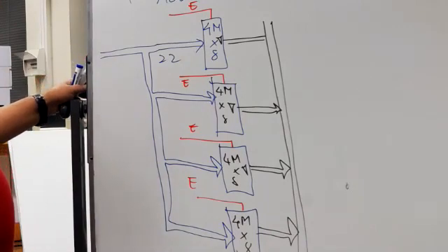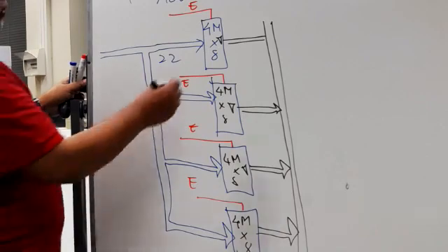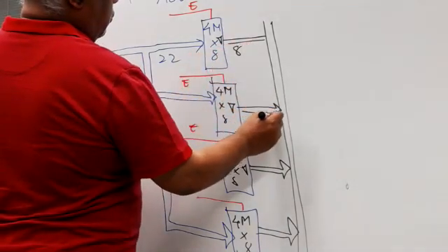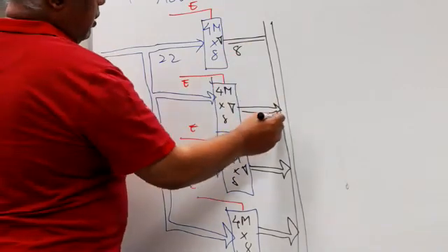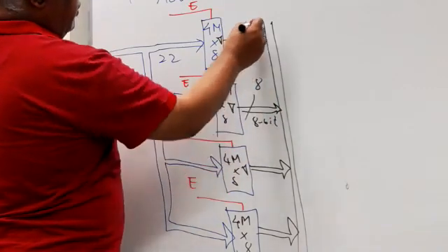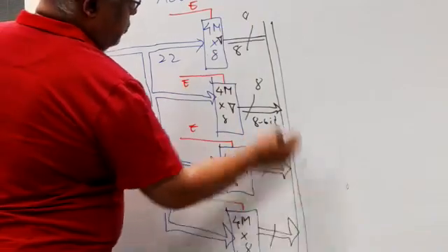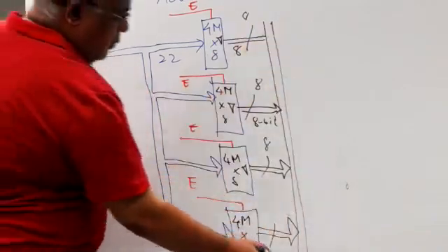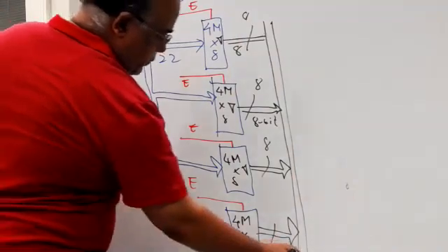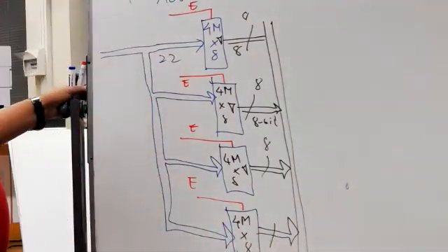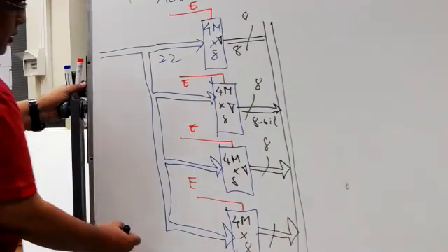Since all of them are 8-bit data buses, that's why you are using this tri-state very nicely. This tri-state property of these ICs, they become very handy. So this is the main data bus probably coming from the processor. This is an 8-bit data bus.